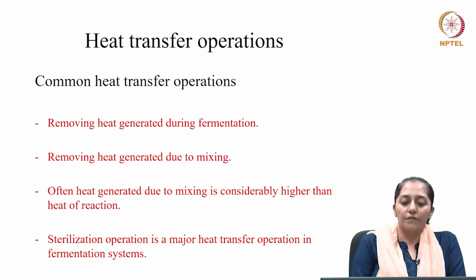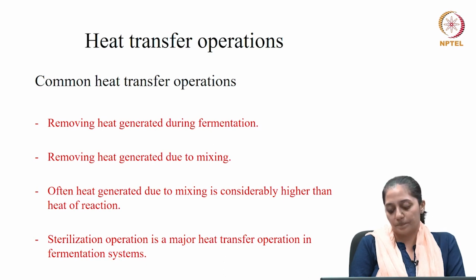So, the common heat transfer operations include the removal of heat generated during fermentation, and removing the heat generated due to mixing, especially in stirred bioreactors. Often the heat generated due to mixing is considerably higher than the heat of reaction, which is your metabolic heat. Now, the sterilization operation forms the major heat transfer operation in the fermentation system.